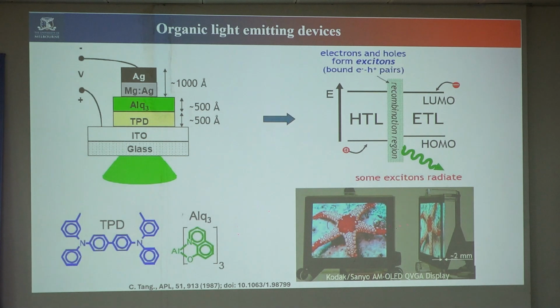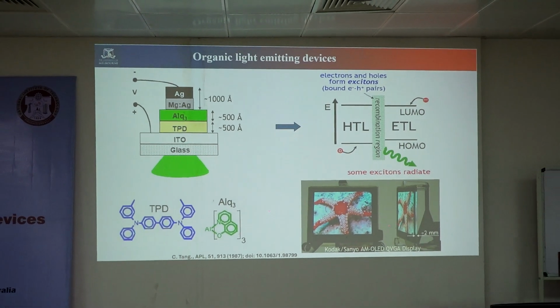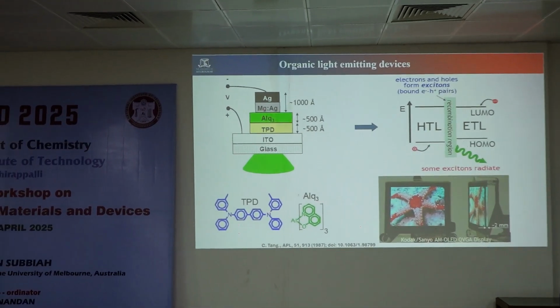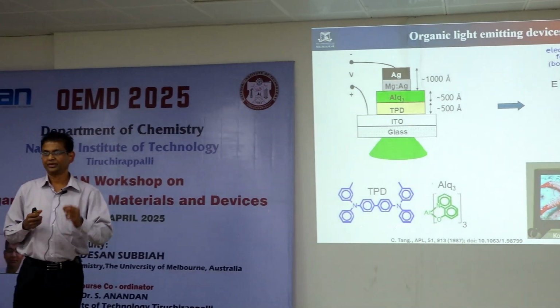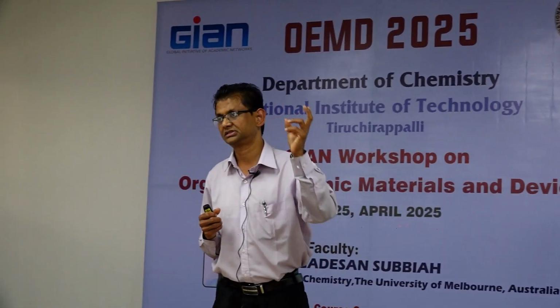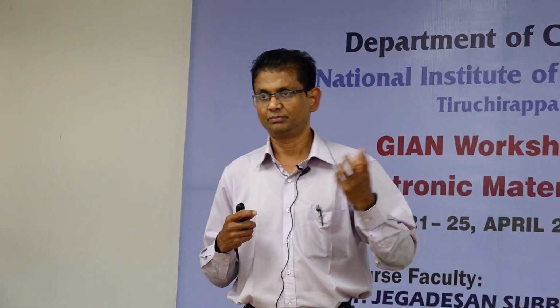In all optoelectronic devices, the OLED case is the reverse mechanism of our organic photovoltaic. Here we generate holes and electrons. The active layer material, the photoactive material, what is it doing? We forcefully recombine these holes and electrons. Then the exciton will recombine and the light will be emitted. The emission wavelength of light depends on the band gap of the material. I discussed already why the band gap plays a role in terms of absorption as well as in terms of emitting light.